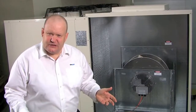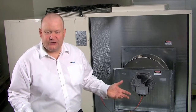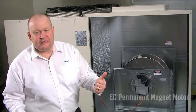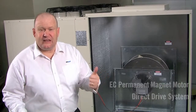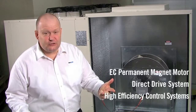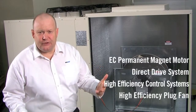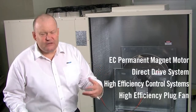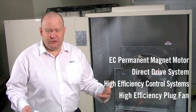So let's put all those energy efficiency improvements in the new technology together inside the air conditioning unit. First of all, there's the EC motor, the permanent magnet motor, which is more efficient. Secondly, there's a direct drive system. Thirdly, there's high efficiency control systems. And fourthly, there's the high efficiency backward curve plug fan. Now all of this together allows the air conditioning unit to run at much higher efficiency than the old unit.